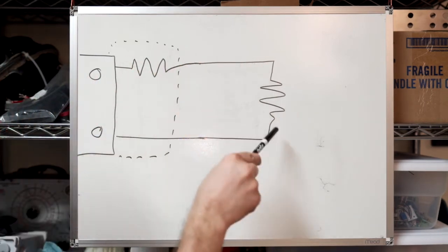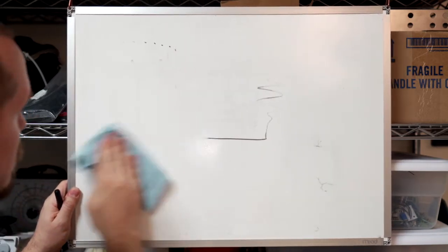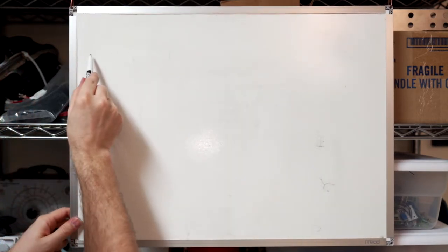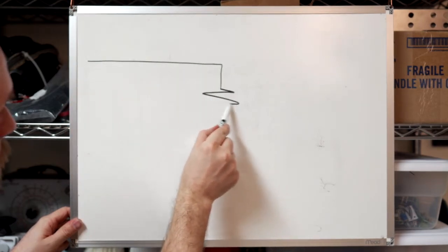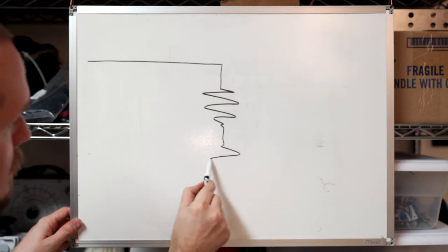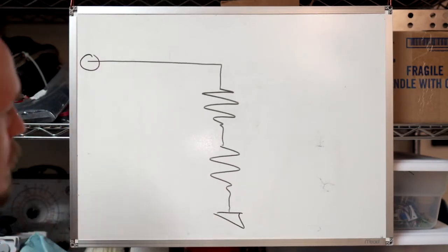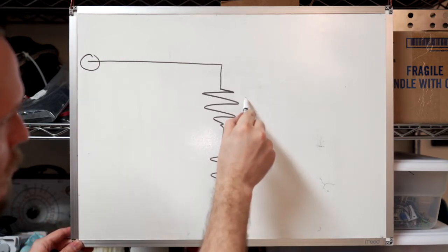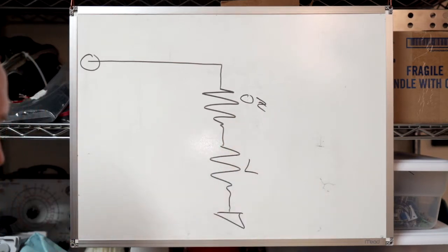As you can start to see now, it's not that hard to do. We've got two values here, and so this can be redrawn as just a simple voltage divider. We'll have our input here, and then we'll have this resistor, and then we'll just go like that, right? And so this is going to be the load, and this is going to be the output impedance of the amplifier, so I guess Z out. And we're trying to discover what this value is.